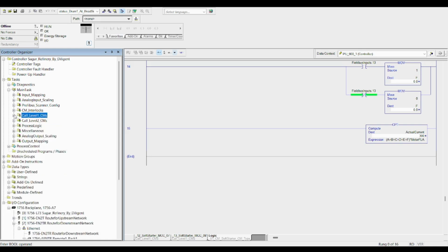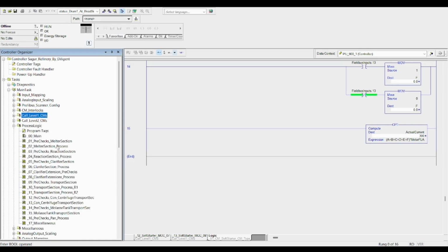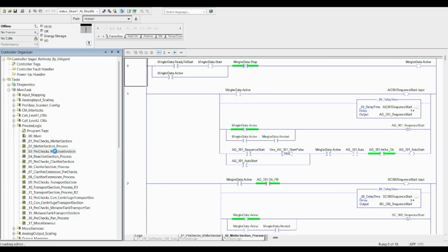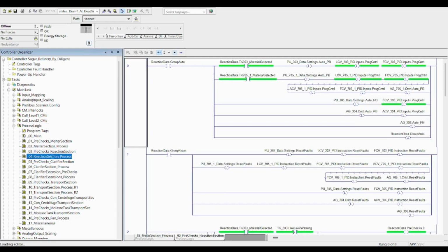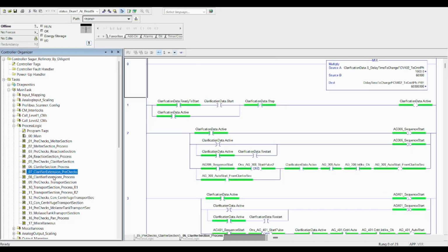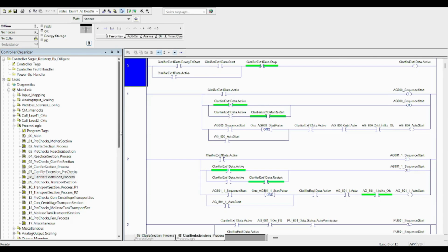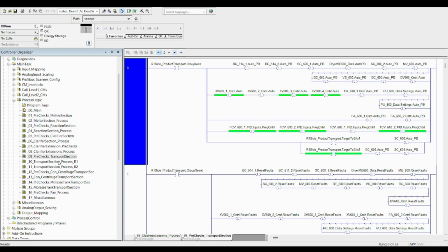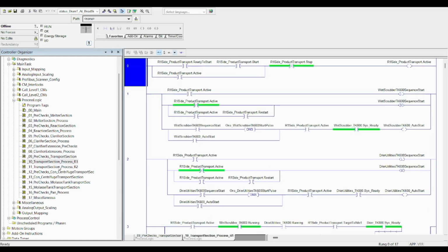Above the control modules are the equipment phases. An equipment phase coordinates multiple control modules to perform a complete process operation. Instead of directly operating individual outputs, it supervises the sequence by issuing commands to the required control modules and monitoring their responses. This creates a clear separation between device control and process sequencing, resulting in software that is easier to understand, maintain, and expand.